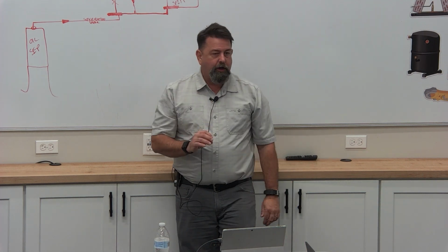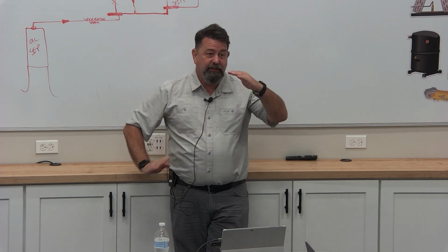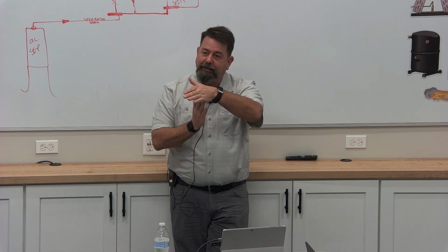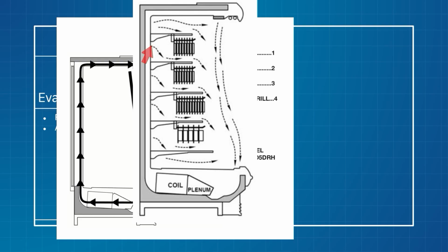So in order for that to work and not blow that air out into the sales floor, I must hit something, a shelf. That air is going to smack that shelf and deflect it down. It's going to take that velocity out of it. And that's where I'm going to get my down angle. That's why it's showing a down angle right here. It's because this air is coming up, it's hitting that, and then it's all down from there. So most of that is going to be nice, gentle downflow.